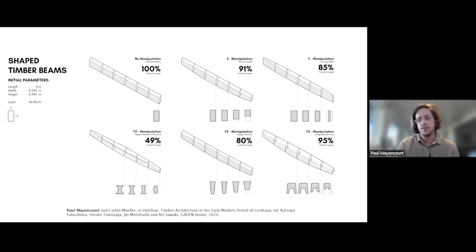So the U section here, you can have a trench for lighting or some other systems, but you can also decide to have simple modifications based on the kind of fabrication techniques that are available to you. Sometimes it will be difficult to manufacture this. It will be easier to just change the height of the beam or the width of the beam. And you can still get pretty significant savings of maybe 15% reduction if you change the width of an element. Or you can go for more complex sections like these at the bottom that have either bigger savings or more interesting aesthetic or design features.